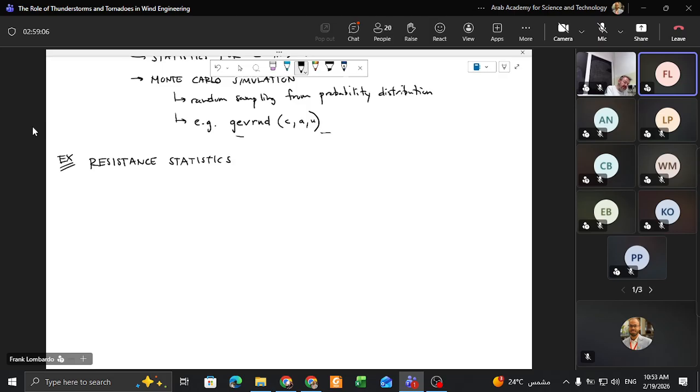Okay, resistance statistics. I'll show you a figure in a second from the slides; this is going to be important for your homework. What you'll see are resistances of 2 nail types. These are driven into the wood panel and connected to the roof truss. You'll see nails named 8D and 6D. 8D is a larger, longer nail, so you'll see it has more resistance.